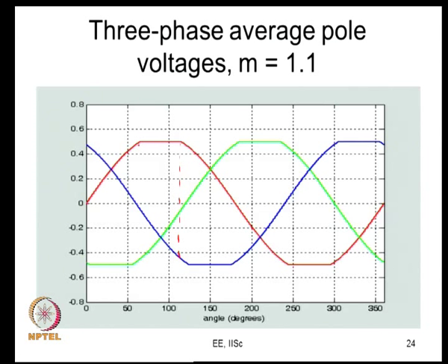This is the region during which R phase is not switching. So, you will see pulses on the R phase PWM waveform here, but you will see no pulses here. The top gate device will be continuously on. Similarly, if you look at the R phase PWM pulses, you will see that it is continuously off here. The top device gating signal will be continuously low, the bottom device gating signal will be continuously high. And so, there are pulses here and there are no pulses here, and that is why it is called pulse dropping. So, this pulse dropping begins.